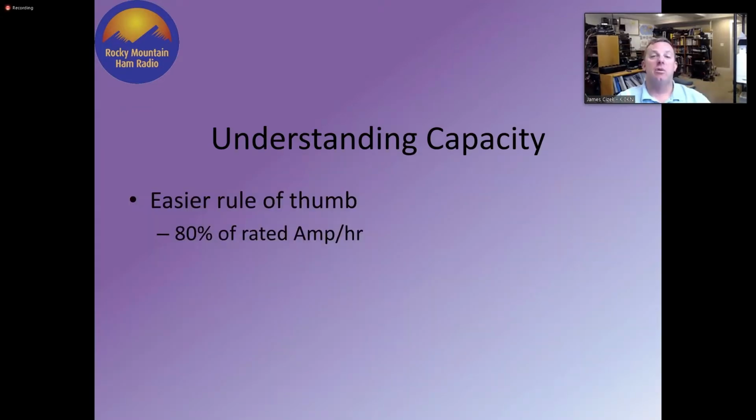There's a lot easier way to just make a quick guess. Use 80% of whatever the rated amp hour is, and that's a pretty safe capacity that you can expect to get out of your battery under almost all circumstances, as long as you're not using it for welding.